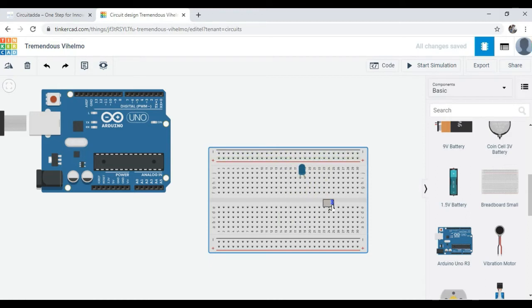First of all, before using a breadboard, you need to know how the connections will be there in the breadboard, right? You can see here there are some vertical lines and there are some horizontal lines in the breadboard, right? So the top two horizontal lines and the bottom two horizontal lines are used mainly for the power supply, and it is not compulsory that you have to use those particular lines for power supply. You can also use these lines for connecting the devices, but in most of the applications, the top two horizontal rows and the bottom two horizontal rows are used for giving the power supply, right?